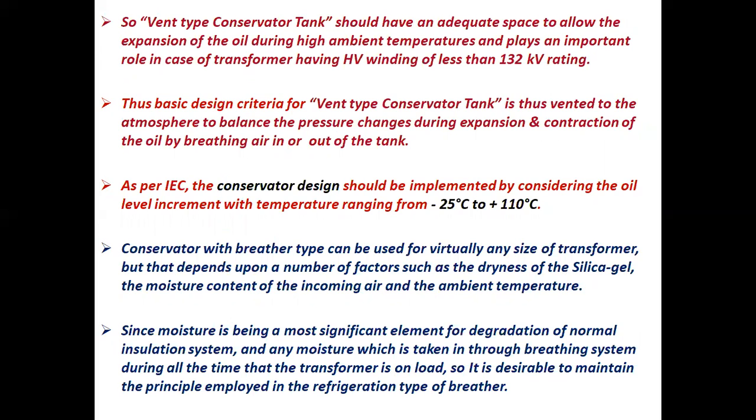Thus, the basic design criterion for a vent type conservator tank is that it is vented to the atmosphere to balance the pressure changes during expansion and contraction of the oil, by breathing air in and out of the tank. As per IEC, the conservator design should consider the oil level increment with temperature ranging from minus 25 degrees centigrade to plus 110 degrees centigrade.